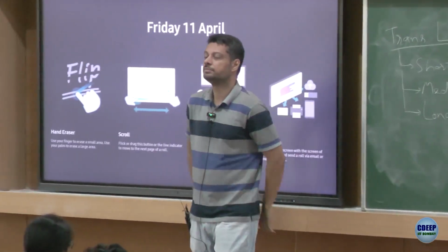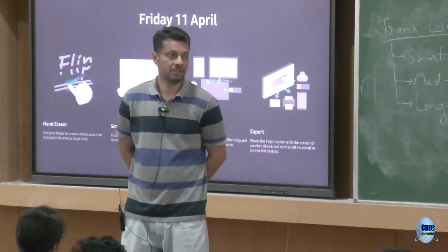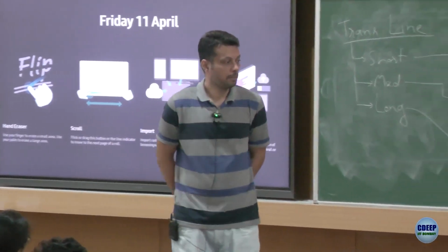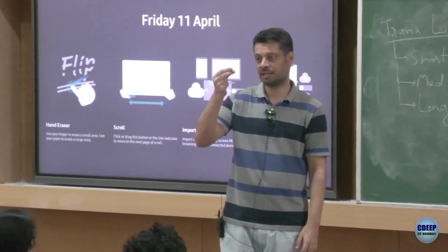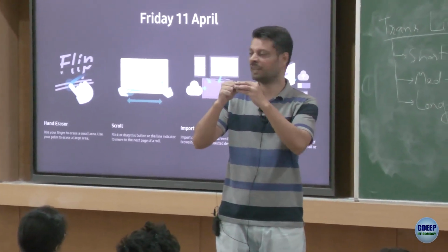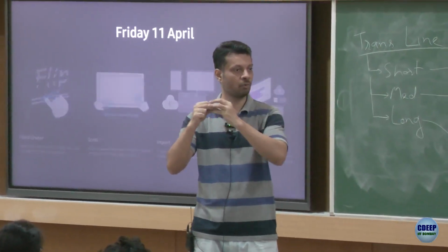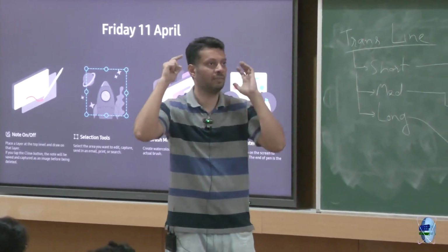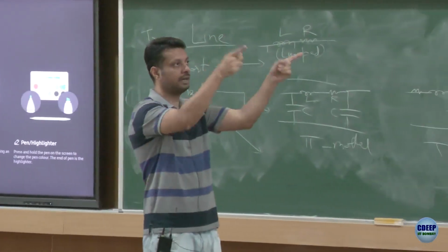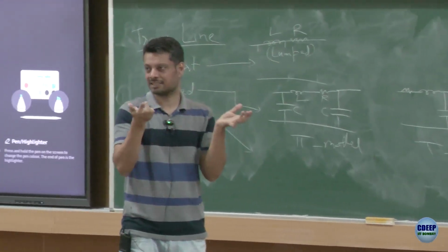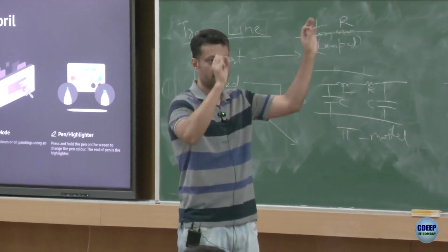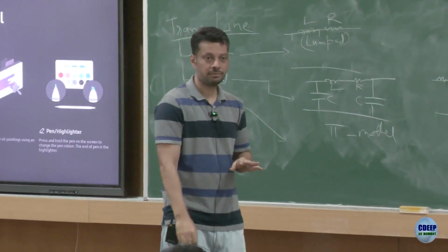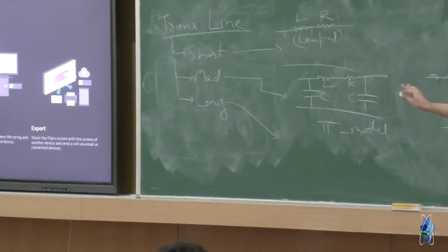If you have a cable versus a line, right? What is a cable? A cable is where you have plus and minus, or you have three wires if it's a three phase, all very closely packed through insulators, and then overall there is an insulation, and this is what we call it as a cable. A line means they are mounted up, they are going ahead, there are no insulations, air itself acts as an insulator, right, and they are placed far apart from each other. So that is a line, this is a cable. Is that okay? These are all parasitics here, all the L, R, C are parasitics here.